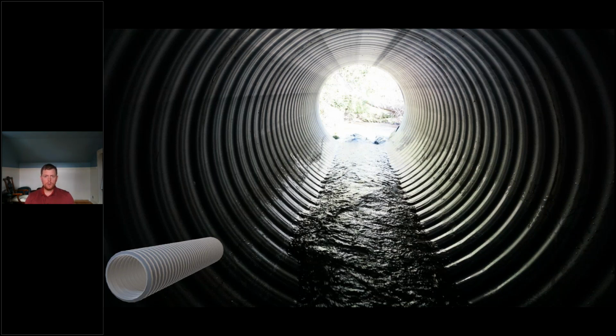You can see that there are some corrugations growing in this pipe. It's been in the ground for about 10 years. On a 48-inch pipe, these corrugations that are starting to show up on the smooth inner liner are probably anywhere from a 1/4 inch to a 1/2 inch deep. So that corrugation is going to impact the flow of this pipeline. So as a designer, I would probably put this above the concrete Manning's n. So if concrete's at 0.012, I certainly would not design this pipe for anything less than a 0.015. I might even trend a little bit closer to the CMP, maybe that 0.018.